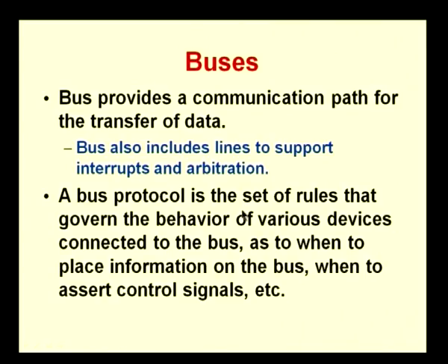A bus protocol is a set of rules that governs the behavior of the various devices connected to the bus as to when to place information on the bus, when to assert control signals and so on. When the data can be placed on the bus, when the data can be taken from the bus, all these things are controlled by means of a bus protocol. So, whenever we have any bus that is designed, we would normally have a protocol that goes with it, which we need to understand to see how exactly data will be transferred to and from the bus.